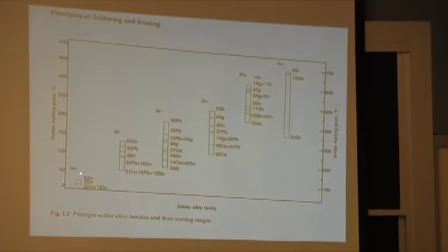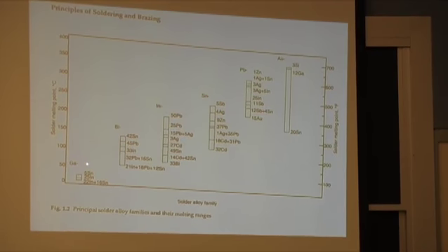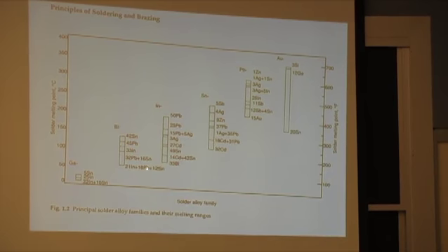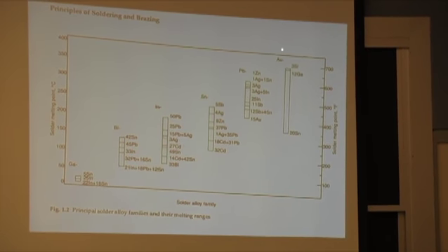Well, it turns out you can look at different families of solder. So here, gallium solders with tin, indium and tin, bismuth, indium, tin, lead, gold. Gold with silicon, germanium, and tin forms very deep eutectics. And gold tin is often used for bonding semiconductors to their substrates.